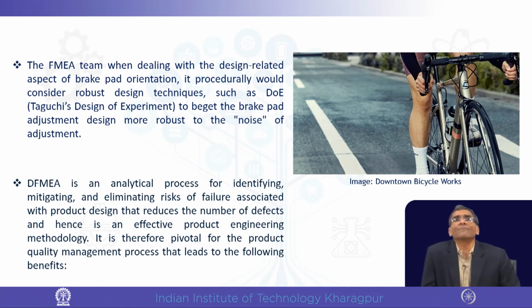The FMEA team, when dealing with the design related aspects of brake pad orientation, would procedurally consider robust design techniques such as DOE, Taguchi's DOE, to make the brake pad adjustment design more robust to the noise factors. Noise means this: in the condition of rain where it becomes slippery, yet it should have a firm grip.